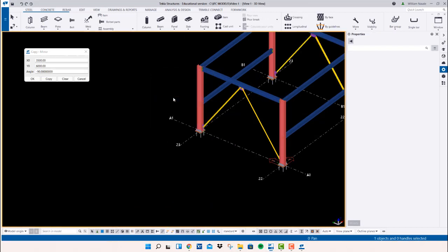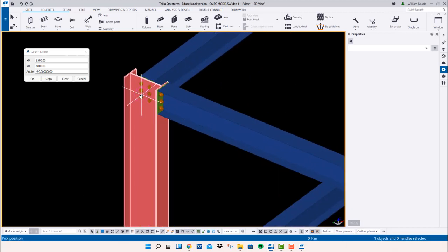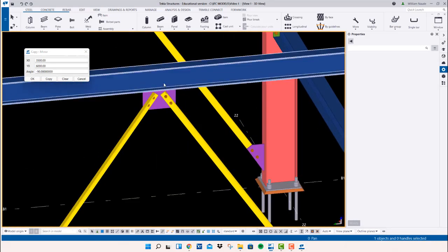There we go. Right, it's probably a bit late in the video, but I'm going to explain to you how I rotate once more. You have more than one way. You can either press Control R, choose your point, hold in the Control button with the middle button, and you rotate. Choose interrupt, or you can just go to a point that you want to rotate around. Let's say this spot right here.